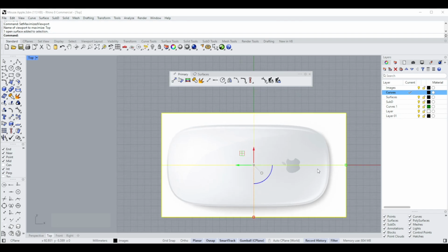And we're going to do the same now with this top view sketch. But at the moment, if I select that sketch, you can see that the arms of the actual object are obscuring that line. So it's difficult to see what I'm doing. So let's move this line out of the way by selecting it, clicking on this move button, and saying 10 or so, something like that.